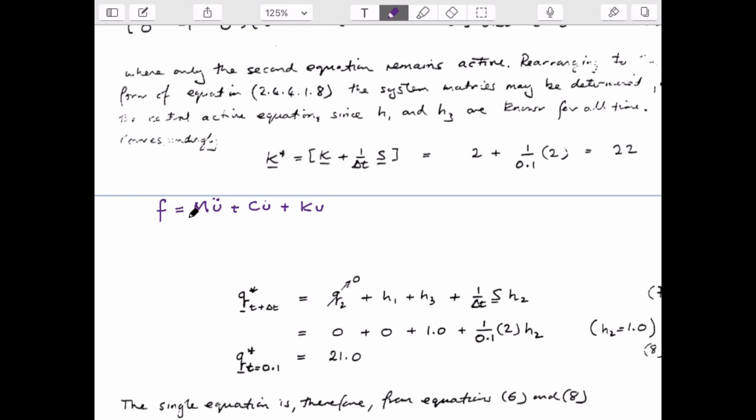So we've kind of seen, in our particular system, we're solving something that looks like flux is equal to storage times head gradient plus conductance times head. These are our dependent variable matrices. So this is the problem we're looking at now.